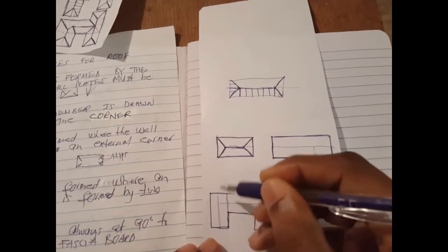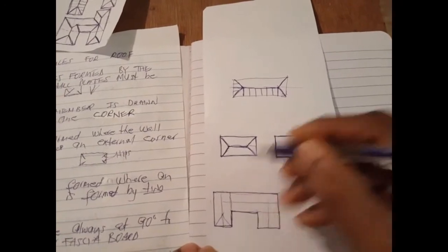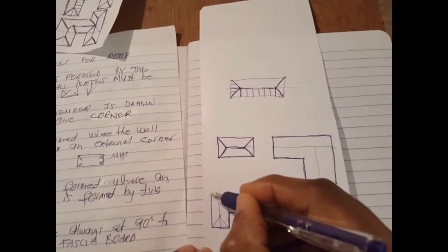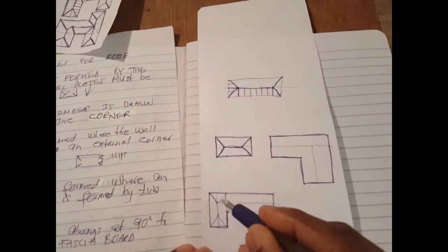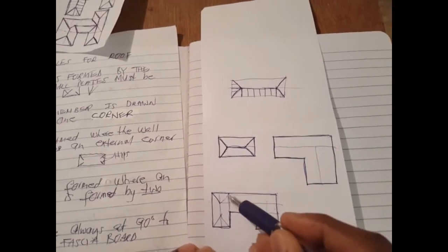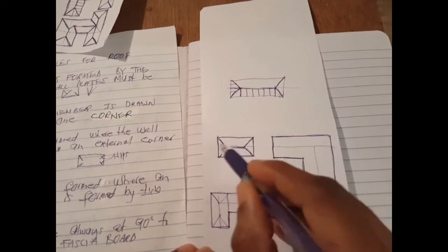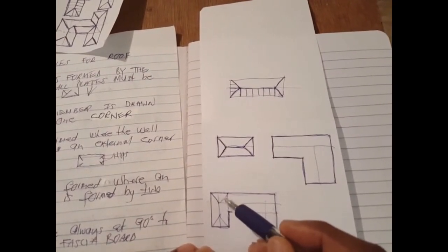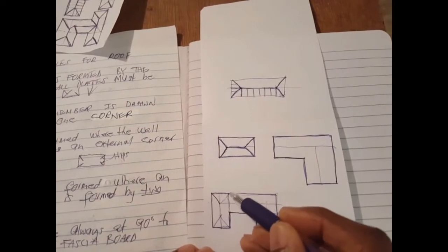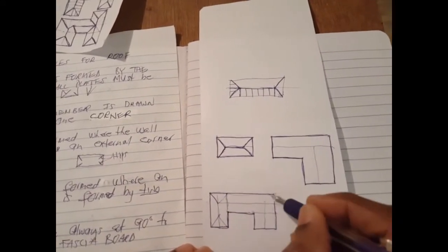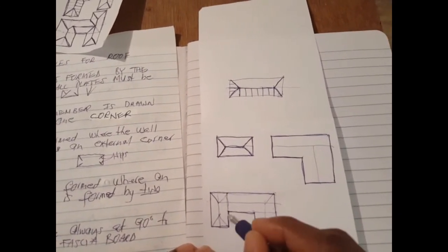So we have one rafter here. Remember, we must draw these at 45 degrees. So the first one being drawn at 45 degrees. Here we draw this one, and we are going to just draw this one for drawing's sake, because the rule states that for each rectangle we must have a complete roof outline like this. Even though we know that this wasn't generated from a corner, I'm still going to draw it. All right. This one also, we draw this at 45. So this now would be our complete one right here.